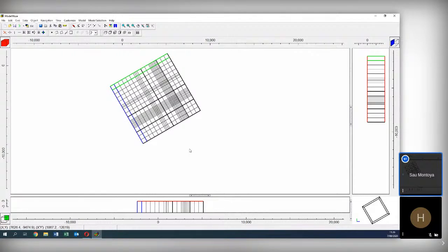It could be the flow direction, the basin shape, or any boundary condition that you want to reflect. This is discretional to the groundwater model. You can also do the model on the XY grid, an unrotated grid, but it really depends on you.